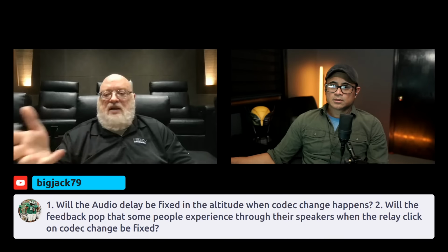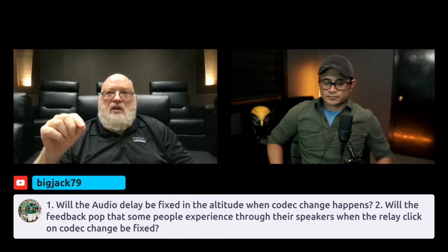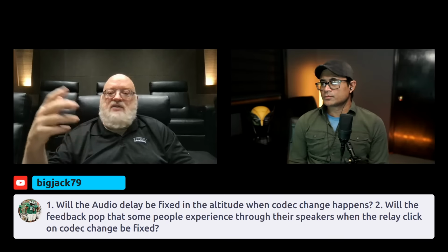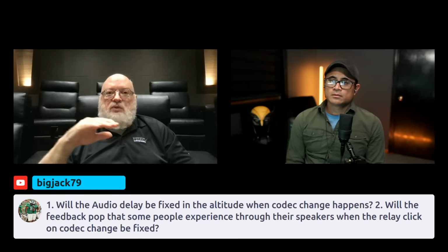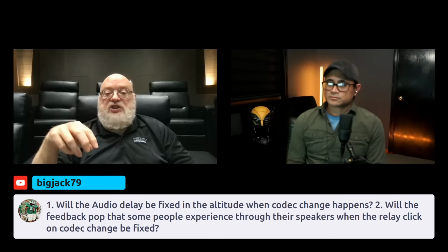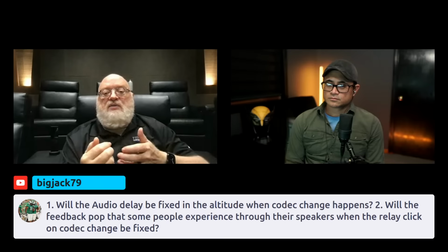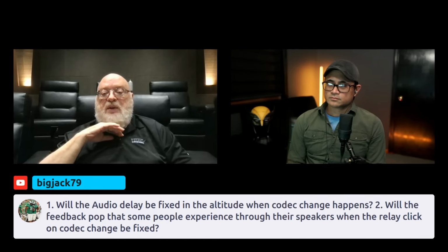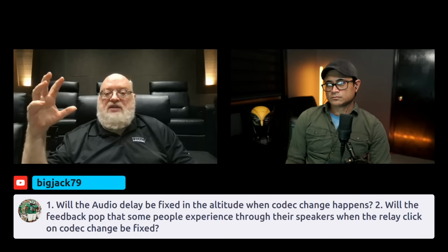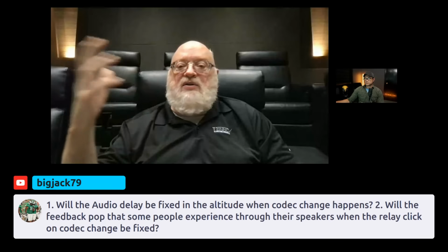The reason, oddly enough, Shane and I were talking about this earlier, the reason some of those processors from Denon, Marantz, Yamaha, whatever, switch as quickly as they do is that on their HDMI board they have a scalar chip, so that no matter what comes in, what goes to the TV is always the same. And that means the TV, never seeing a change, never has to initiate another EDID handshake and HDCP and all of that stuff.